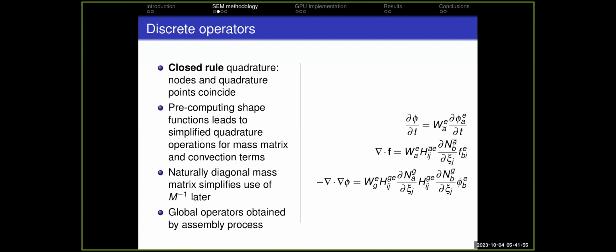Those elemental operations, once they are carried out, are combined into an assembly. So we assemble local elements into a global array or global mass matrix and global residuals for the convection and diffusion operators. And in case we have a mesh partition over multiple CPUs or multiple GPUs, we use point communication between the arrays using very simple MPI send receive routines to ensure that each partition knows the information that it has to be communicated prior to following up with either a Runge-Kutta step or with some form of an implicit method that we can also implement.